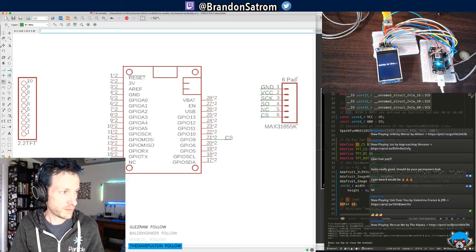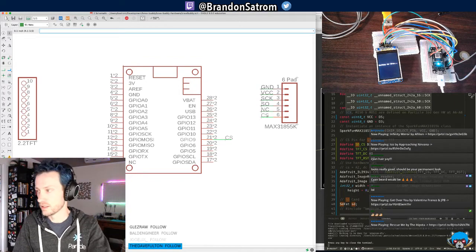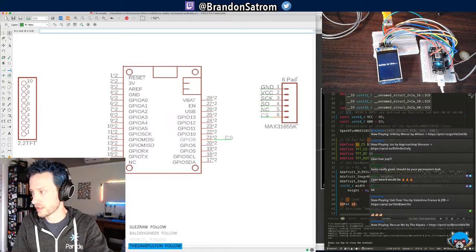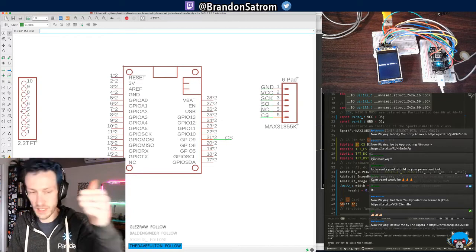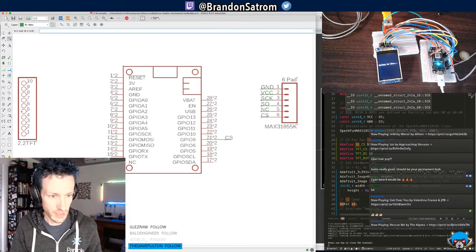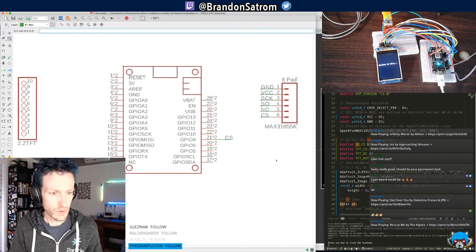So now the nice part about that is if I click on the show icon here in the upper right hand corner and then click on CS, it'll actually highlight the CS down here, you can see it in sort of a lighter green. So it shows that those two are indeed electrically connected, which is what I wanted. So that's the first one.